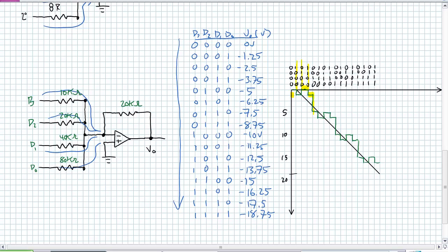And as you progress through, you'll see this repetitive pattern. It goes up, back down. So that's non-monotonic. It should go as we continue to progress from 0, 0, 0, 0 all the way up to quadruple 1. We should see that nice constantly increasing, but we're stepping back in time. And yes, the answer is D1 is constantly being held in a 0 position.